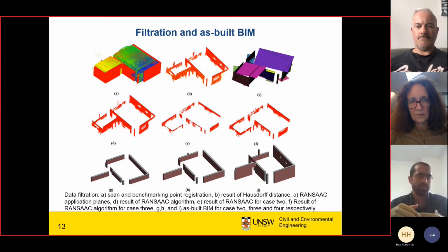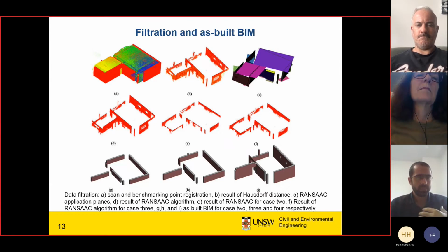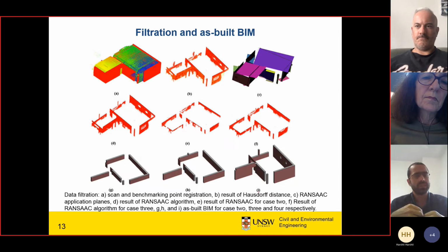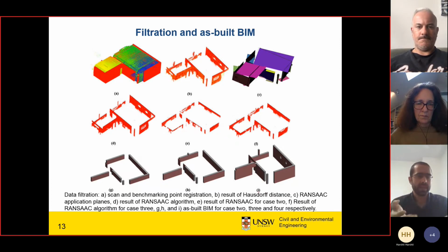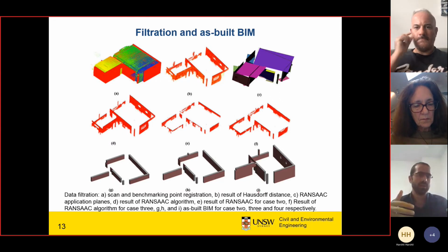From the STL format, we can then convert to a point cloud in CloudCompare. But in the second case study, we extract only the inner surfaces of the wall, not the outer surface, because they are not included in the site scan. So we are using Dynamo to extract those surfaces. Again, we convert that to STL format, and from STL we convert directly to a point cloud.